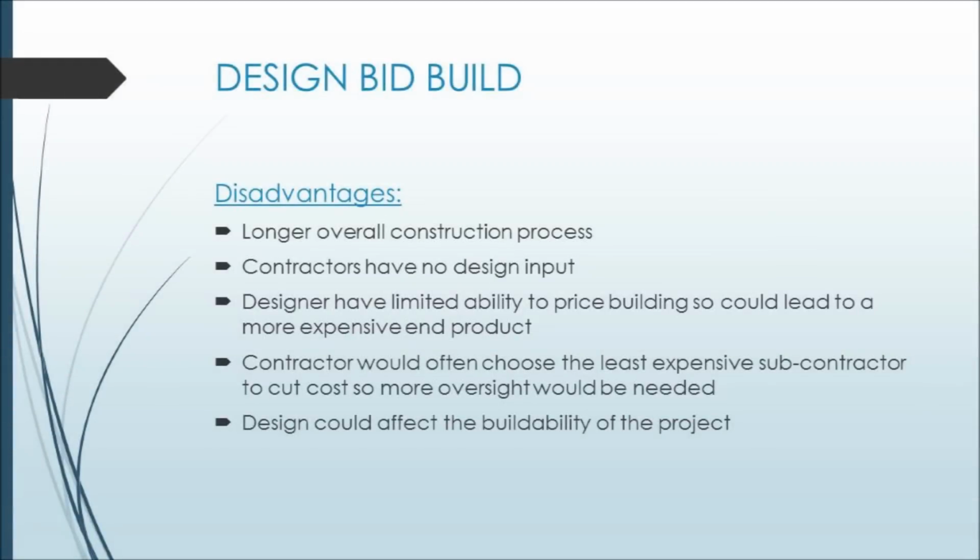Now for some disadvantages. This method has a longer overall construction process, as it is linear. This means the design has to be finished before construction can start. And during the design process, contractors have no input, which could potentially lead to buildability issues during construction.